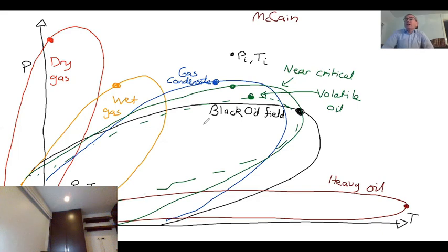And the technical reason is actually how we describe oil and gas fields. So, in principle, a hydrocarbon accumulation is a mixture of hundreds of different chemical compounds. And how we might describe them thermodynamically with an equation of state, if we want to put an equation to this phase behavior, is by understanding the behavior of these hundreds of molecules and their interaction between them.